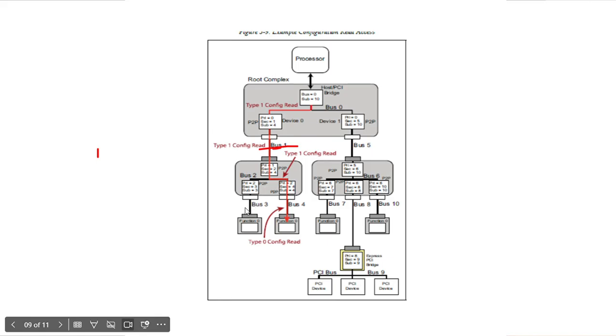It will read bus 3. This host bridge will insert the config traffic to bus 3. It is initiated. Here this is the last point, which is the endpoint. After reading the vendor ID and header type, header type 0 indicates the endpoint. By reading the header type it will come to know this is the endpoint. This is the last stage. No need to be configured.